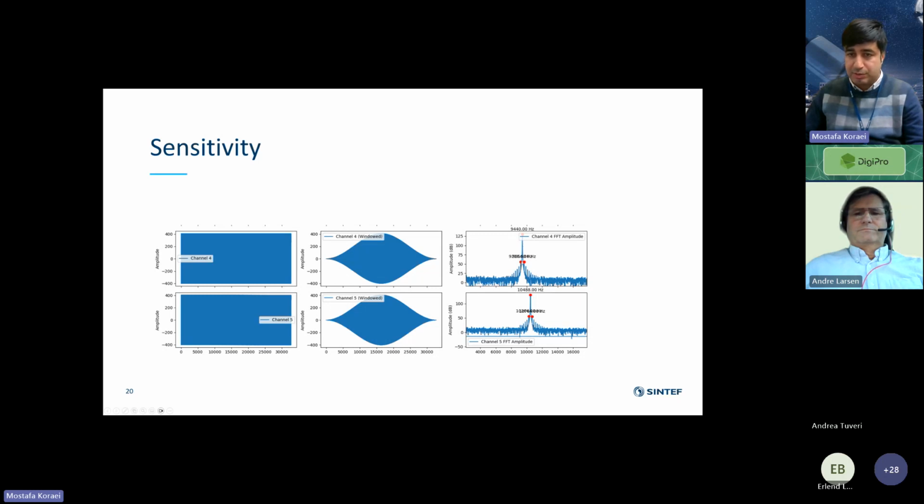What we were looking for is these two red dots close to that, at 9.44 and 9.3, at very close frequencies, but with more than 60 dB difference. So even if the external noise is 10,000 times higher than the signal we are looking for, we can detect that.